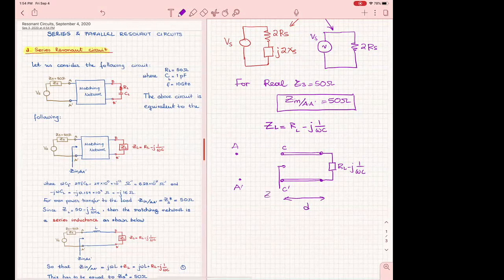the input impedance at that point, remember, is given by this: if this is Z naught, Z naught times (ZL plus j Z naught tangent beta D) over (Z naught plus j ZL tangent beta D). What kind of a number is this? Is it real, imaginary, or complex for our case? What do you think?